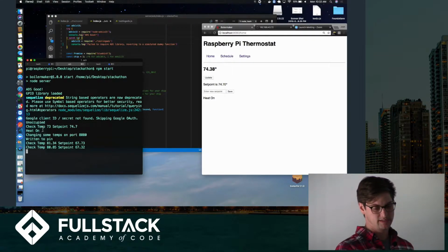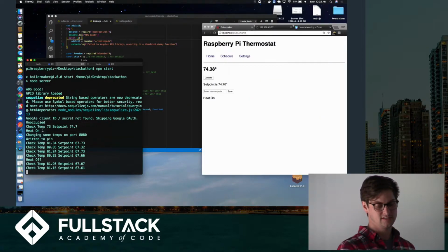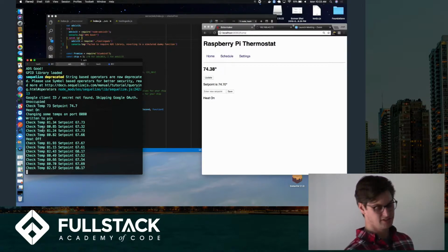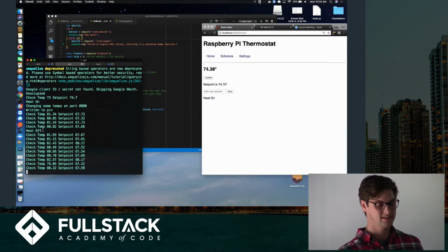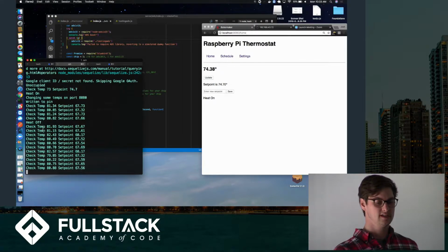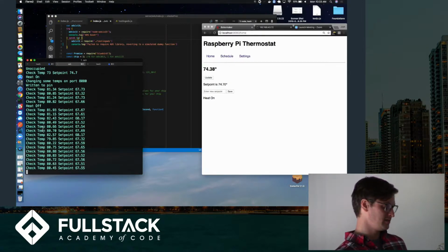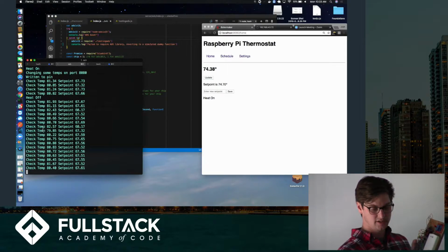But so there, it's basically console logging the current value of the temperature, and you can see it says it's 82 degrees in here. It's not accurate because I've got a battery source here, so that's a bug I just realized, that it's using a reference voltage, and because that reference voltage is lower on the battery, it's actually improperly calculating the temperature.